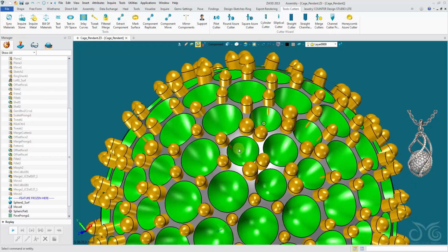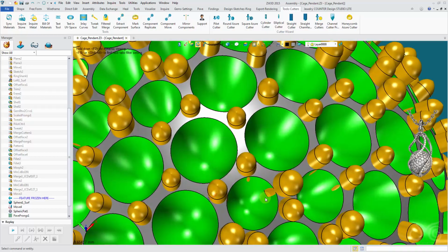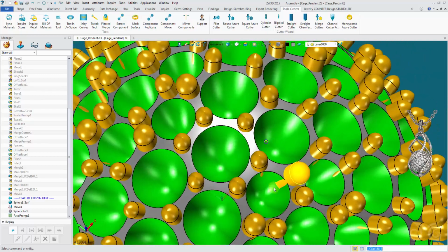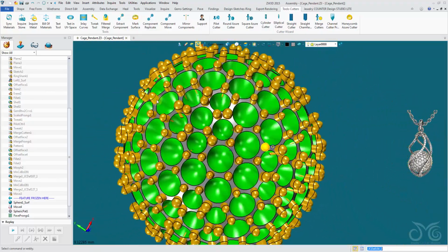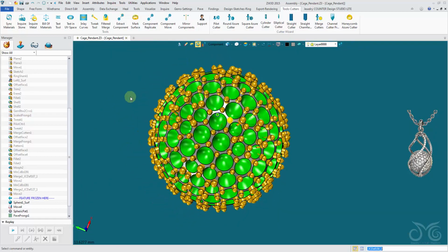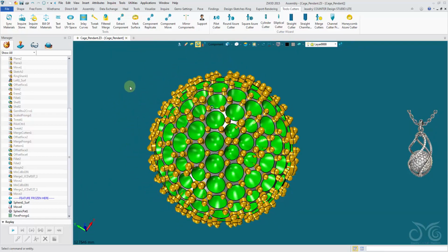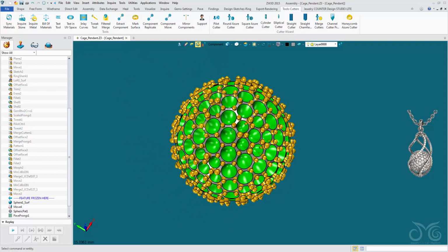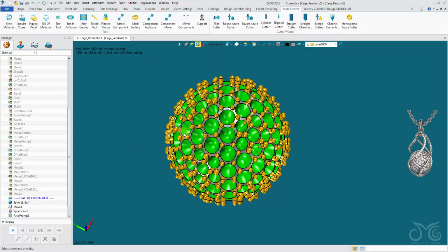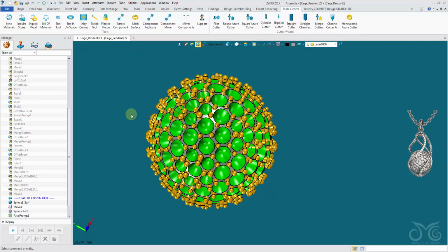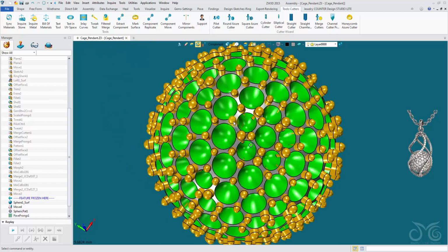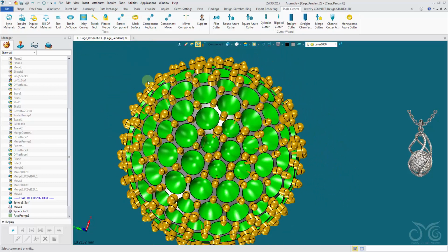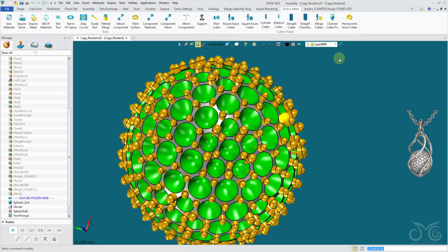Okay, they go pretty deep there. Let's see if our prongs will merge nicely. There's a chance they may not. We have potential for many coincident faces here. Now, if we were to manufacture this Pave sphere, you may want to manufacture it in two halves, so you can hollow it out. You can have a shell, reduce your metal weight. You could solder the two halves together. Alternatively, you might want to drill down, deepen these cutter holes to reduce the amount of metal weight.